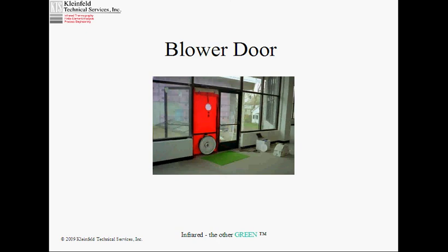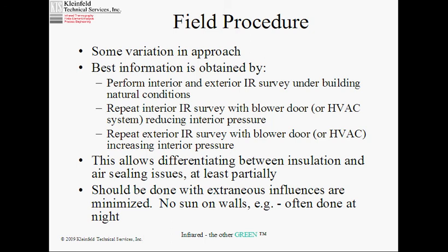This is a picture of a blower door. You see the fan on the bottom. This particular blower door has a nylon panel with a view window, so you can see if somebody's trying to come through the door. Not shown on this is the instrumentation package that goes with it that tells you the differential pressure and the flow rate through the fan. As shown, the fan here has a cover on it, which has to be taken off either in stages or completely to actually run. The way it's shown, it's still sealing the house the way a closed door would.